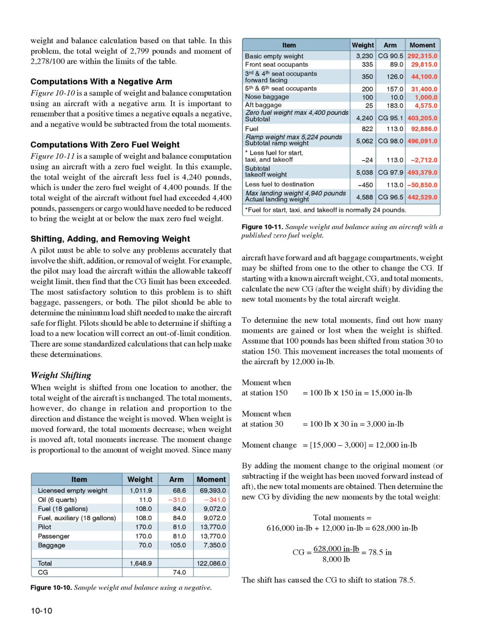Shifting, adding, and removing weight. A pilot must be able to solve any problems accurately that involve the shift, addition, or removal of weight. For example, the pilot may load the aircraft within the allowable takeoff weight limit, then find that the CG limit has been exceeded. The most satisfactory solution to this problem is to shift baggage, passengers, or both. The pilot should be able to determine the minimum load shift needed to make the aircraft safe for flight. Pilots should be able to determine if shifting a load to a new location will correct an out-of-limit condition. There are some standardized calculations that can help make these determinations.